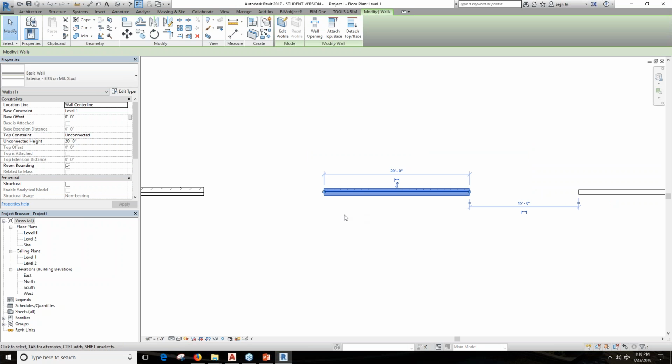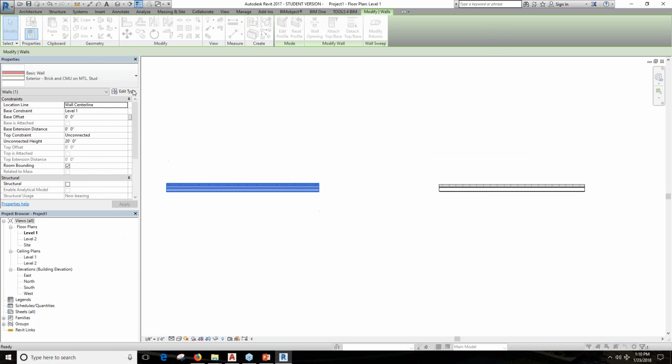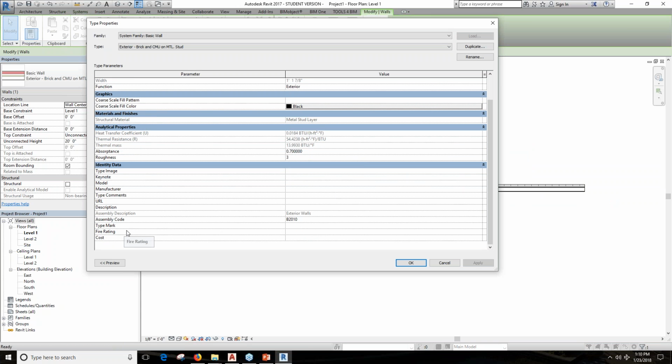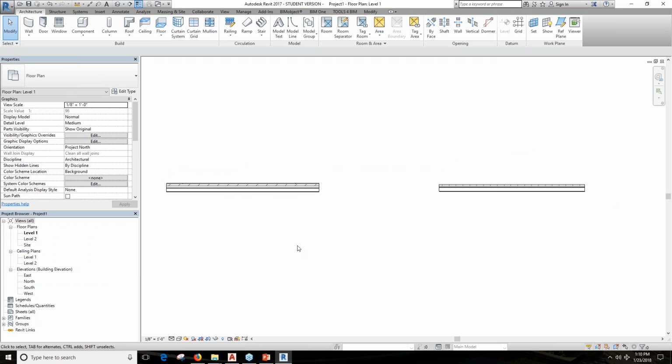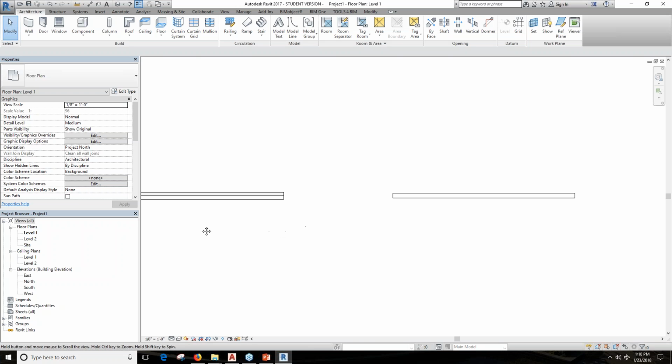That's why I placed 3 of them different, so that you can see where you can locate the fire rating, and how we can assign it. Well, if you are coming from an AutoCAD background, most likely you represent those fire ratings in a floor plan or even in a section by creating a hatch. And that can be done here in Revit.